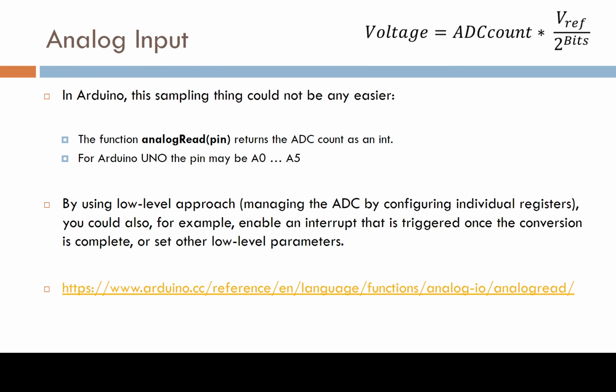Okay, back to Arduino. So the previous was in general about sampling. Sample fast enough, or remove any high frequency components before sampling.